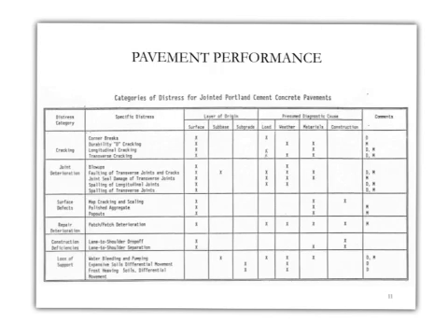And then we can see here, this is the layer of origin. It's kind of interesting here that most of the cracks that are related to the PCC really depend on the Portland cement concrete layer. Very minimal that you would see a sub-base related issue or a subgrade. The only thing that's really related to the subgrade would be the loss of support. But mainly, it all depends on the top layer of Portland cement concrete.